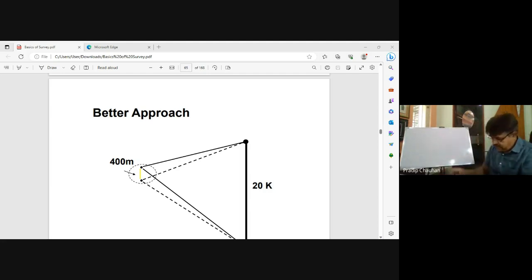If it is a linear survey, say for example you are planning a road in a green field, then you need to go for a reconnaissance survey. You will refer to a Google survey map. Then you will try to draw certain possible alignments. Then you move across that alignment, try to move out of that, and you will find what hurdles are there. First you will go for the feasibility survey. Once you find that this is feasible, then you go for the preliminary and detailed survey.